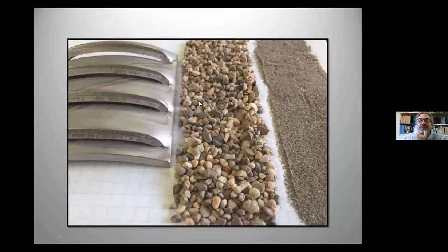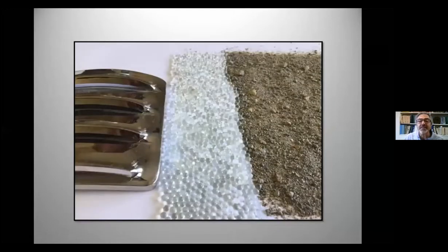And this here would be a represented gravel pack whose, if you want to think of it this way, lowest third in diameter is 6 to 9 times larger than the lowest third of this formation. And the slot size here is selected, about a 2 millimeter slot size, and it's supposed to retain 80% of this material. So that's how we basically go from the formation to an aquifer to a gravel pack selection size to a slot size.